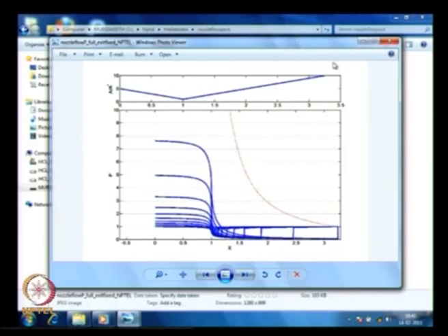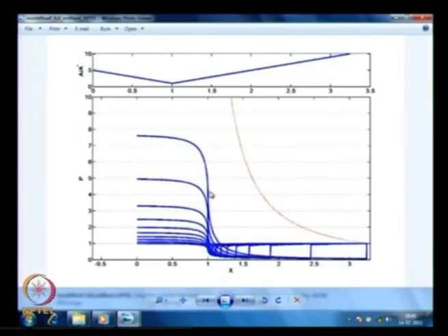We look at this particular picture, where I am having the same nozzle. I have just plotted it differently now. We are keeping the exit pressure exactly the same as the back pressure, and the flow wants to meet this pressure whatever happens. What we are saying is, it starts with a slightly higher value, it goes down and goes back up, it is all merged inside here, you cannot see very clearly. But say about 2 or so, it is going to become supersonic, have a shock and then go through the subsonic path. And as I increase my P naught, now my shock is pushed more downstream.